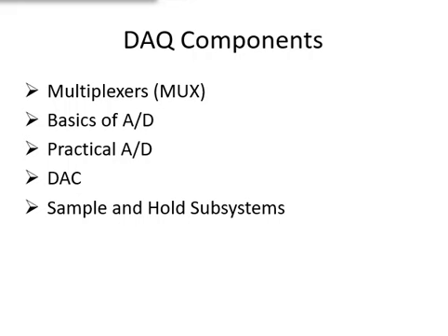To make a computer into a data acquisition system, several additional components are required. Multiplexers and analog to digital converters are almost always present, and other components are added as required. If it is necessary to take readings of several measurements at precisely the same time, simultaneous sample and hold devices or related systems are required.